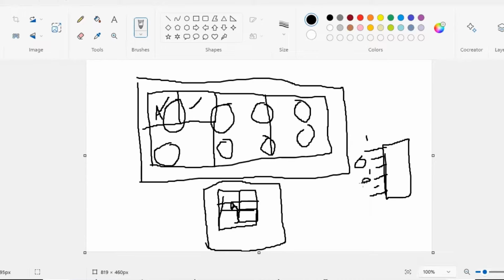This is 0, 1, 0. This is one of the patterns. Like this, we need to give all the patterns to all the inputs. We give one pattern and check the timing, then give another pattern and check the other timing. So it will take more time, right?